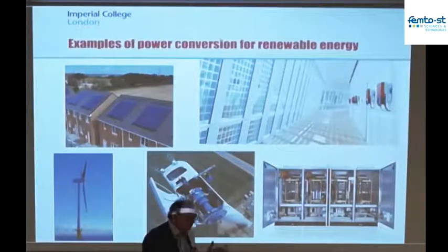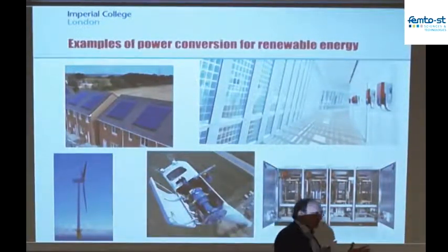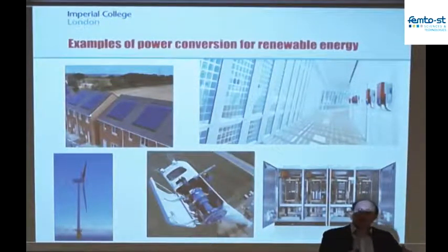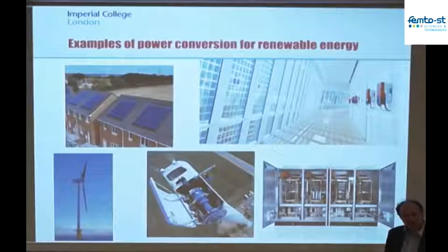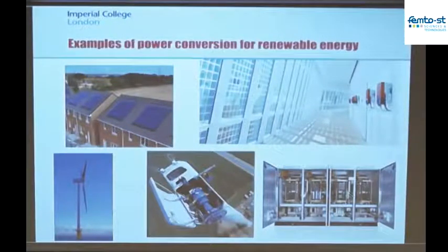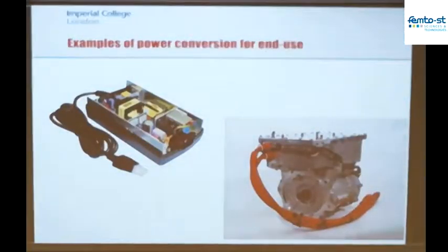You're very used, on standard pieces of electronics, to thinking about the electronics as simply a PCB. It's a fully integrated thing on a PCB. It's very easy to manufacture, and more and more it's all on a single chip. With power electronics, because it fundamentally requires you to be storing and releasing energy from element to element, the thing has to be bigger. And it tends to be built, therefore, of larger discrete components, and it tends to be assembled in a bunch of cabinets, rather than all being on a single circuit board. But of course, it depends.